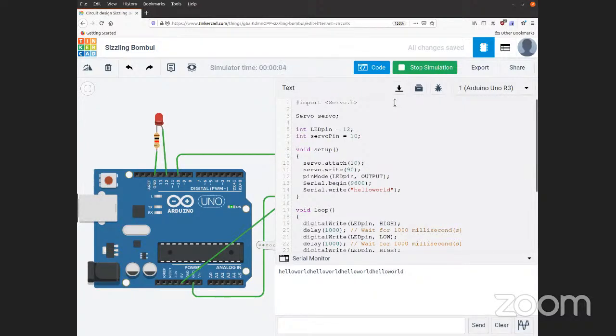There you go. And that's the other reason for having a variable to set your pin. If something happens and you break a pin in that little hole for number 12, you don't have to rewrite your whole program because the hardware broke. You can just cut that pin off, put it into 11, change your LED pin equal to 11, and off you go. And in FRC, that's probably even more important if something gets damaged on the RoboRIO, so that you can very easily switch to a new pin. Hopefully, we won't be running our Elegoos quite as hard as FRC robots.